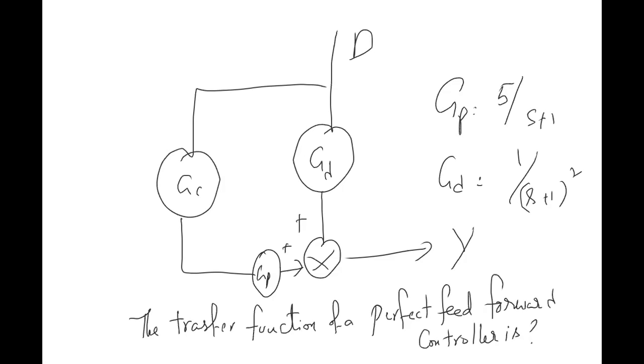So here, what is the response? Here there is no set point. Why is there no set point? Suppose you say that I want to operate my CSTR throughout its life at 60 degrees, then there is no change of set point. Directly y should be equal to 0. If y equal to 0, that means you will put directly y minus 60, that means your small y is equal to 60. So that is how some control loops don't have set points. Why do you need a set point? Suppose I want to operate the reactor sometimes at 60, sometimes 70, sometimes 80, then you need a set point. If you never operate the reactor at anything other than 60, then you don't need a set point. Clear?